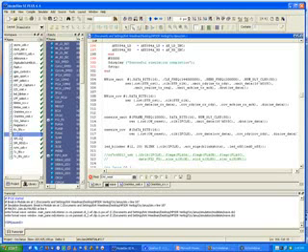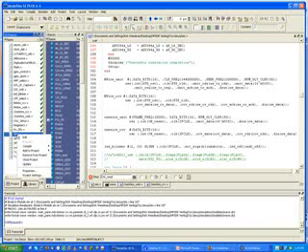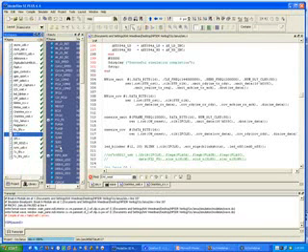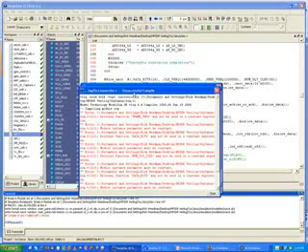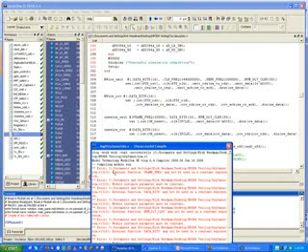Now over here I've got to compile it because it's not compiled. So I say compile selected sim.v, and boom, I get an error. I look at my error and say, oh no, what happened? It says error, external function frame frequency may not be used in a constant expression. Look at line 313.